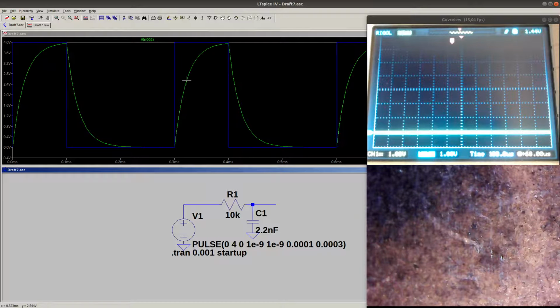Oh, there we go. So that's precise. So 23, and that would be 0.023 milliseconds. And because we're using such a round value for the resistor, that is actually our capacitance here. So the time constant is determined by the capacitor here, which is 2.2 nanofarads.